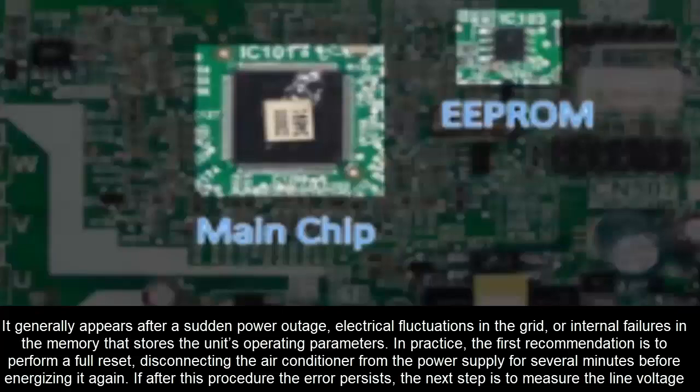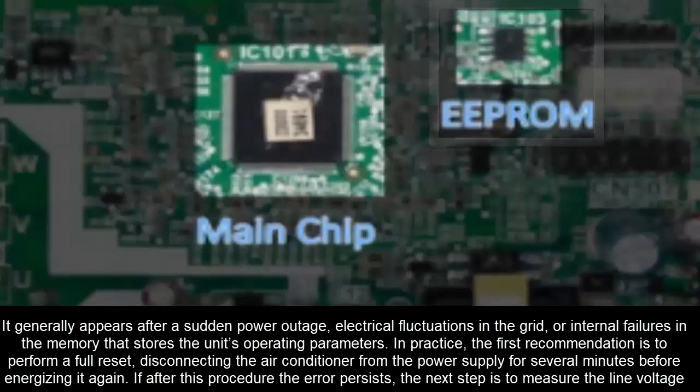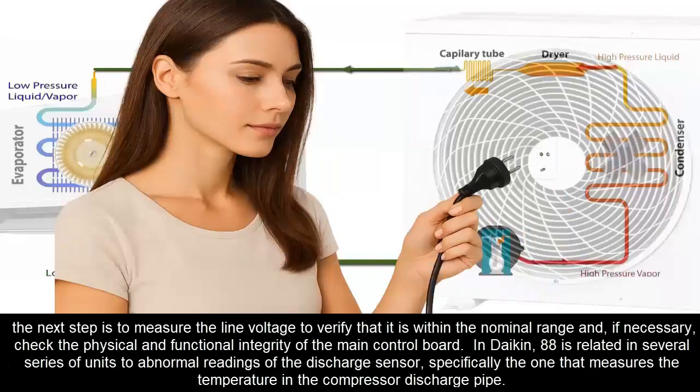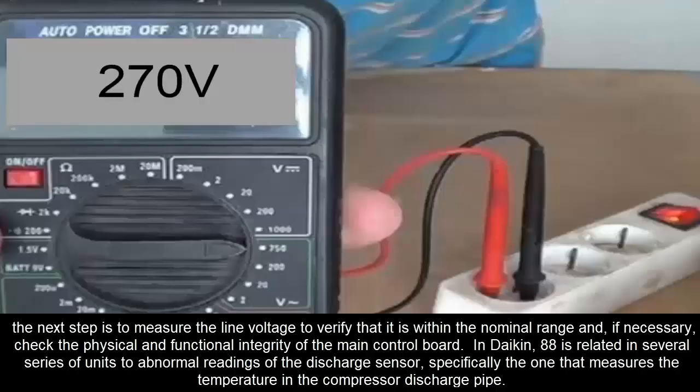In practice, the first recommendation is to perform a full reset, disconnecting the air conditioner from the power supply for several minutes before energizing it again. If after this procedure the error persists, the next step is to measure the line voltage to verify that it is within the nominal range and, if necessary, check the physical and functional integrity of the main control board.